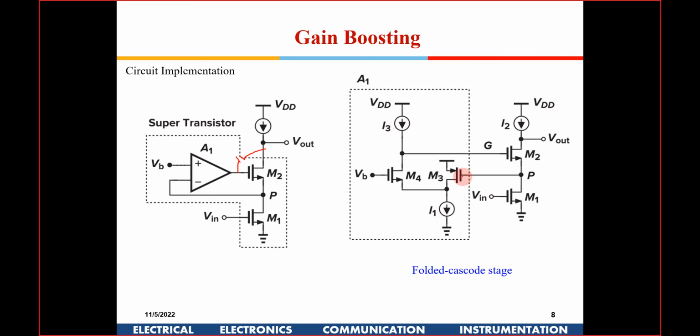You are giving an input to the PMOS. This is a load out here, that is being given to an NMOS here and a fixed bias here, and you are taking the output out here. So you could further improve the frequency response. These kinds of circuits can be implemented, which have higher gains than the traditional single stage amplifiers.